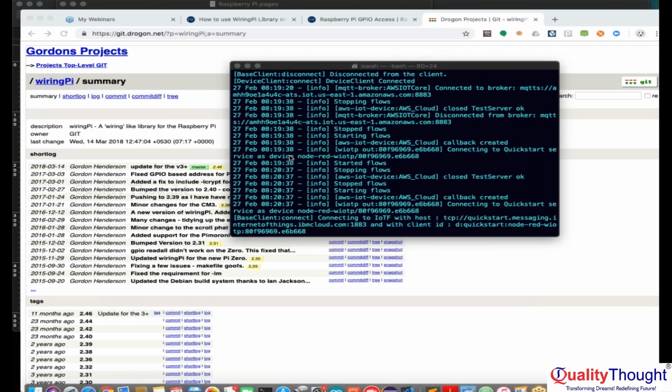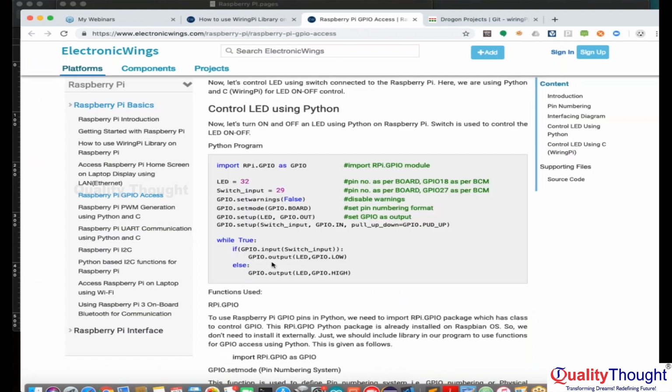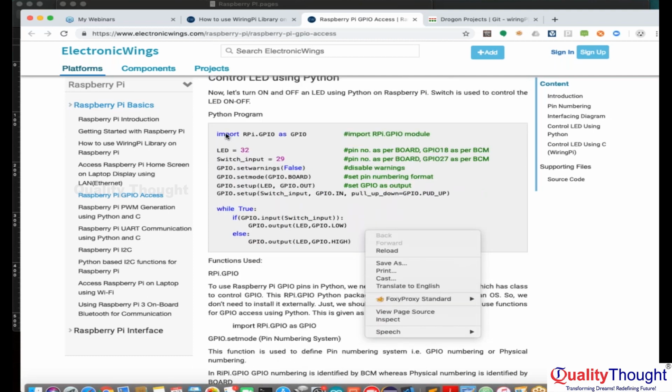That is all about the GPIO application in C. For example, if you want to do the same task with Python, Python is what our concentration is. You can go ahead and import something called RPi.GPIO, which is available on board. By default, Python packages are installed on the Raspberry Pi, so with that you would get this RPi.GPIO package, or module.